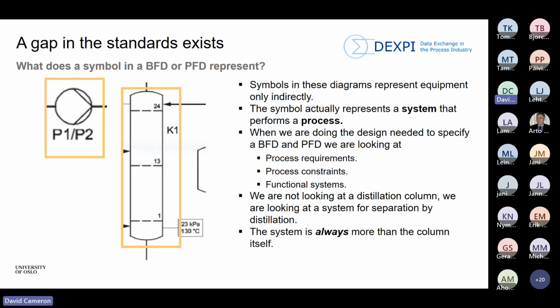Now, what we see is that there's a gap in the standards. That question came up in the DEXPI project by asking, well, we wish to represent block flow diagrams and process flow diagrams. And so the question is, what does a symbol in a block flow diagram represent? It looks like a distillation column, or it looks like a pump. Well, yeah, but actually it's not a distillation column or a pump. It's actually a system that performs a pumping process, or a system that performs a distillation process.